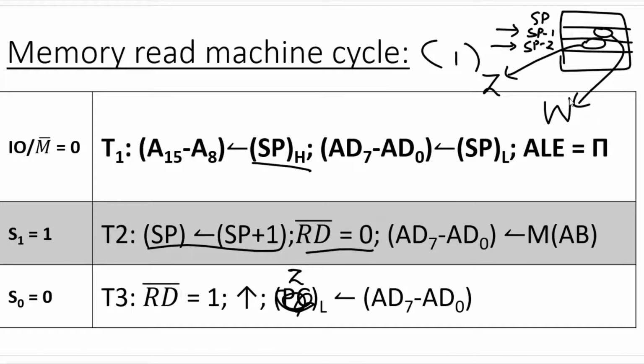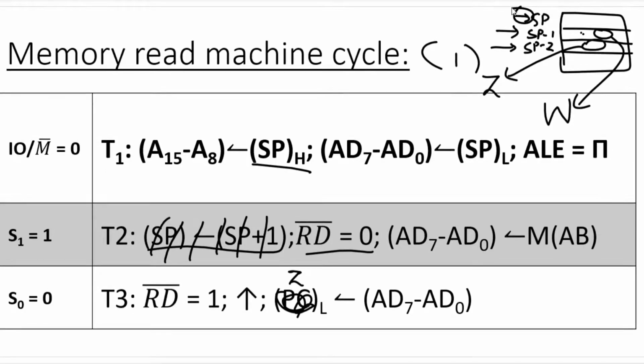Now whatever is in the HL register pair, first whatever is in H, will be read and written to this location. So here, in the second memory read machine cycle, we do not need to have this, because we do not need to increment it and point at this location. We want it to remain here only, so that we can transfer data from H and store it here.